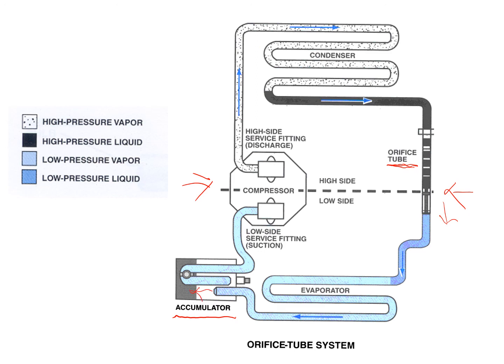This would be vertical, as shown horizontal. So the gas would come in here and then leave through this part, going back to the compressor as all vapor. The purpose of the accumulator is if any liquid refrigerant came out of the evaporator.